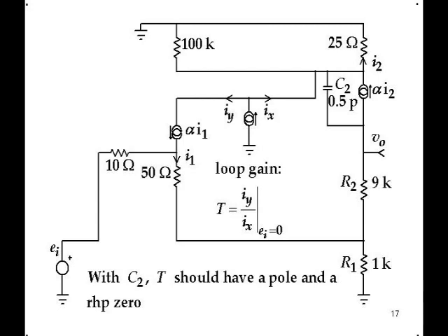Well, there's only one capacitor in the circuit at the moment. So any signal entering the second stage device is going to look into a common emitter or a common source amplifier stage with a capacitor C2, which is in the Miller feedback position.